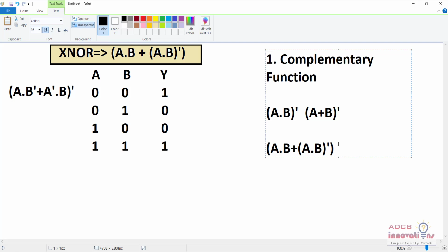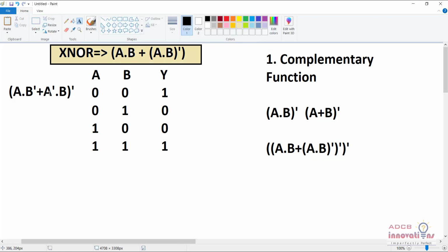So now what will happen is it becomes the XOR gate instead of XNOR. Then again, to make it the XNOR gate, we have to add another complement, that is another inverter. That basically increases the number of inverters and the number of transistors which we are using. So that's why we won't be using this function to make our XNOR gate. What we will do is we will create the XOR gate, and the function will be complementary for XOR if we try to create the XOR gate.